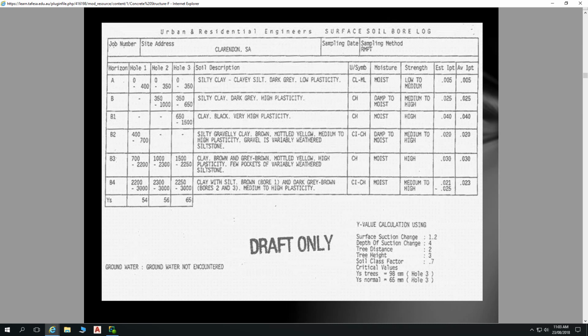So if you've determined that your site doesn't have a sewer connection, and you've got to do on-site wastewater, if you're getting soil samples done, tell the soil sampler also to assess the area that you're thinking about doing your on-site wastewater, because you don't want to pay them $500 to go out there again to take just a 1500 mil sample for the wastewater engineer to work out how that wastewater is going to percolate into the soil. You want to get that done at the same time.